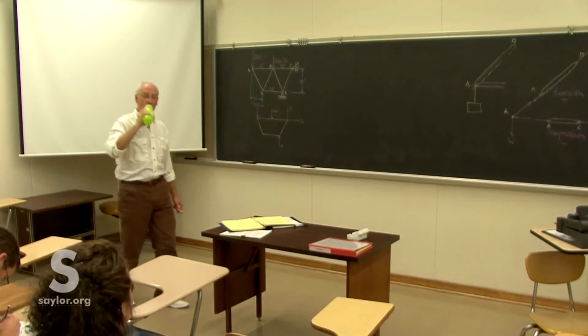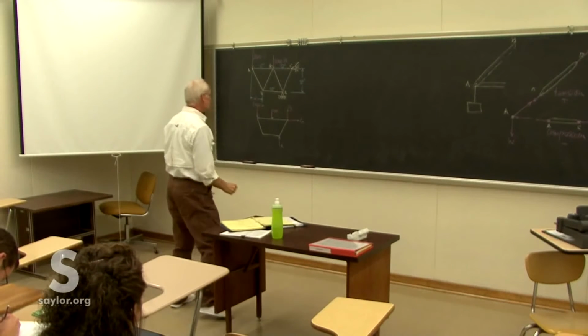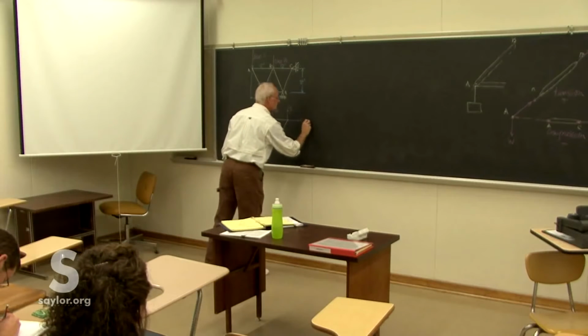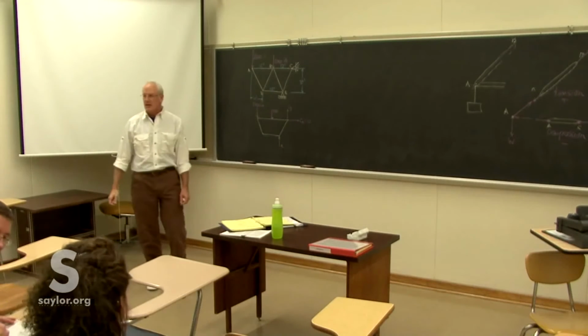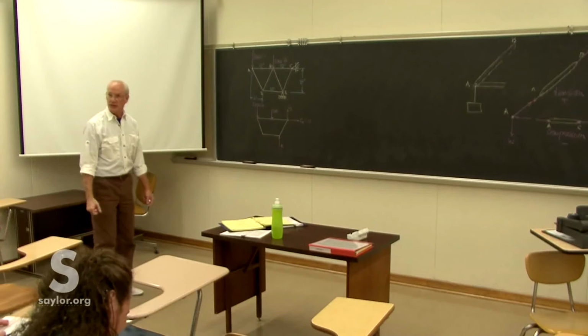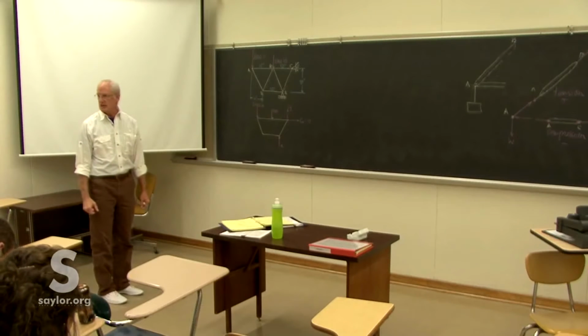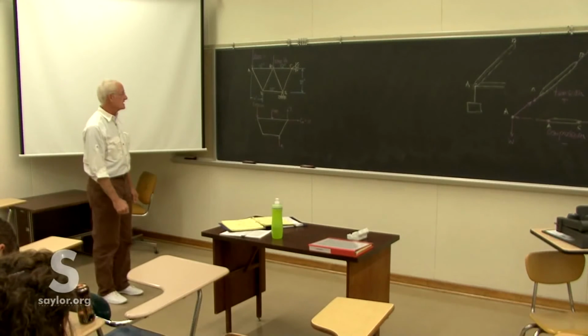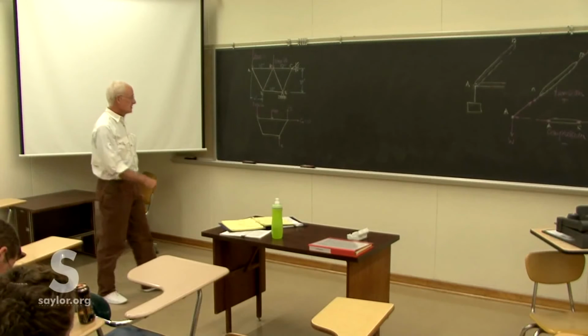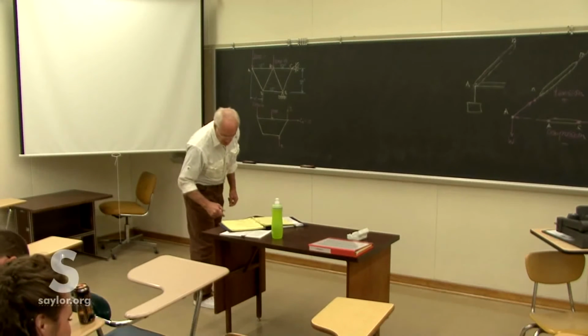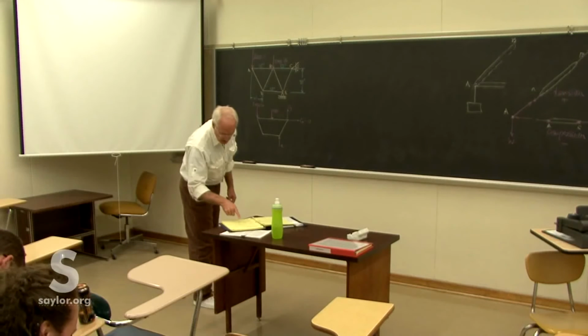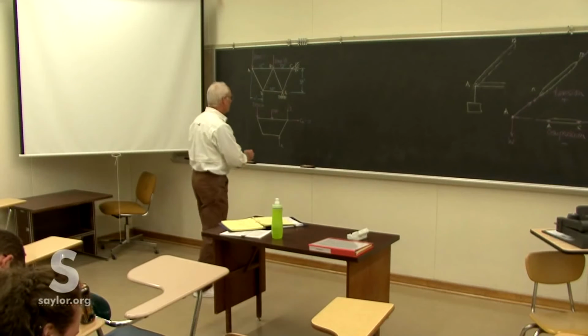X is gonna equal 0. Just by inspection, we know CX has got to be 0. It's not truly inspection. All you're doing in your head is summing the forces in the X direction. That's the only one. It must be 0. And so then we can solve for the other forces.